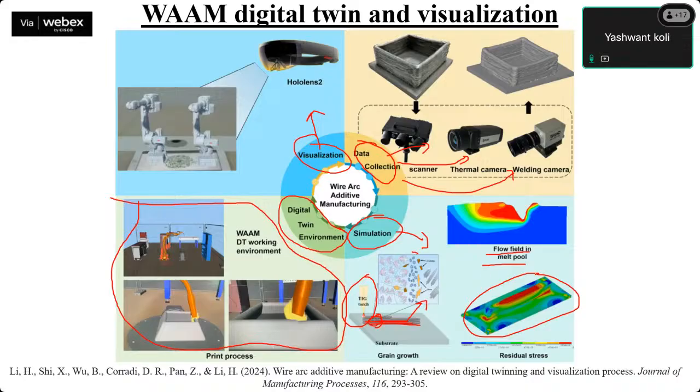Two layers can be delaminated by having tensile residual stresses. So these can be kept minimized. Residual stress can be reduced through real-time data collection, real-time monitoring, and feedback, so that we can avoid bad process parameters and use the best parameters.